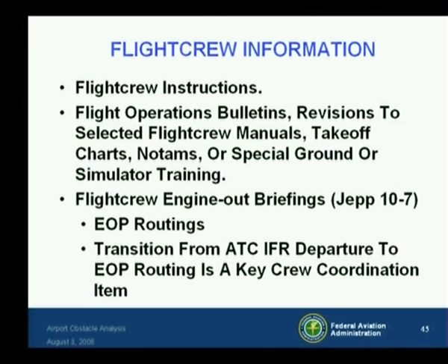Now, EOPs, engine out procedures, do not eliminate the need for flight crew engine out briefings. We're talking here in normal air carrier 121 and 135 operations, the JEP 10-7 page. How or when to transition from an ATC IFR departure to an EOP routing is a key crew coordination item, a briefing item. EOP routings may differ significantly from ATC IFR departure routings, as we saw in the Colorado Springs example.